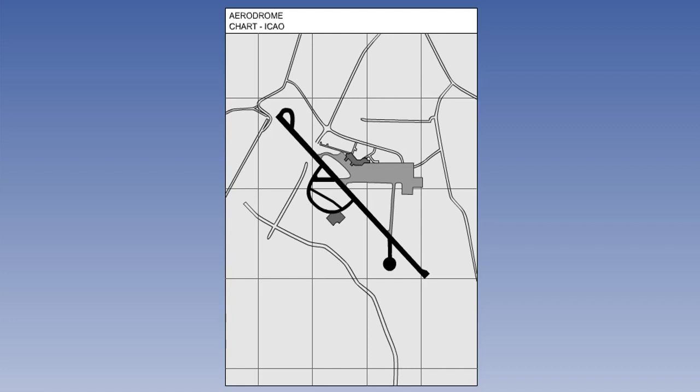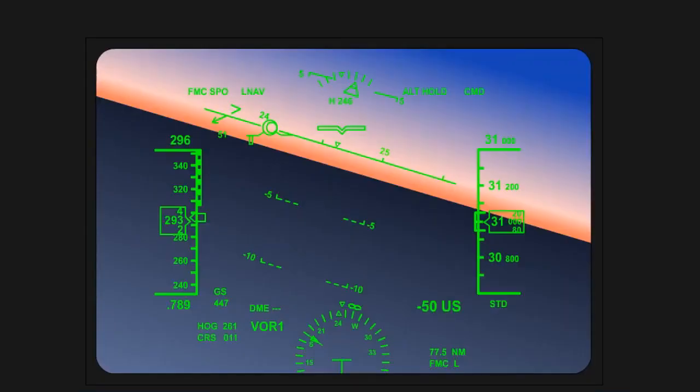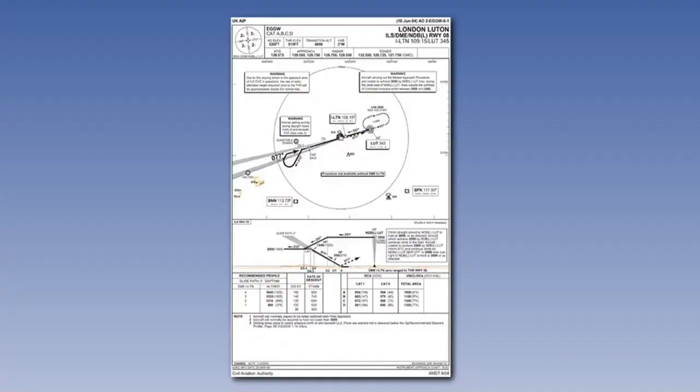These absolute minima are the highest of those specified in EU Ops and by the National Aviation Authority responsible for the aerodrome. With the advent of the head-up displays, HUDs, and enhanced visual systems, EVS, we examined in the last lesson, the state may publish lower visibility minima for these systems or allow operators to negotiate lower minima based upon their demonstrated abilities with these systems. Unless the authority allows otherwise, all approaches must be flown as stabilized approaches, SAP, and, additionally, non-precision approaches must be flown using the Continuous Descent Final Approach, CDFA, technique.